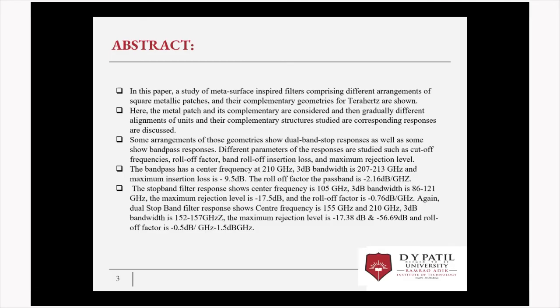Regarding the bandstop filter response which we have in the graph below, the center frequency is 105 gigahertz and the 3 dB bandwidth is between 86 and 121 gigahertz, and the maximum rejection level is minus 17.5 dB, and the roll-off factor is minus 0.76 dB.